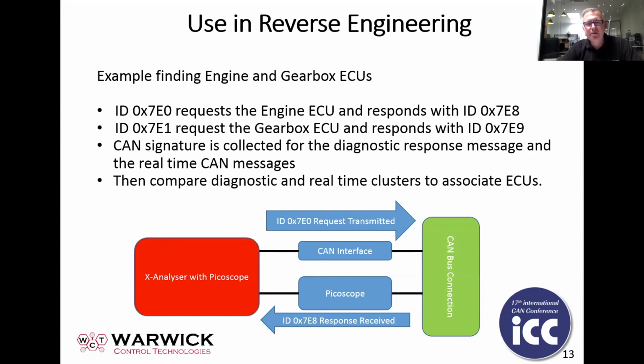You can compare this to the unknown real-time messages which you find on the CAN bus. So you have a process whereby you make the diagnostic requests, you then log the diagnostic responses, and then you carry out the generation of the CAN electrical signature, and then you can examine the clusters and see what compares to what.